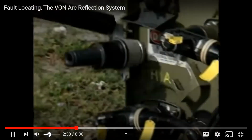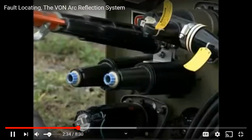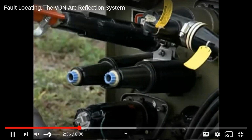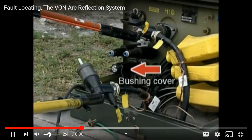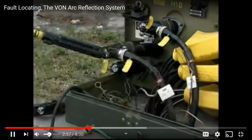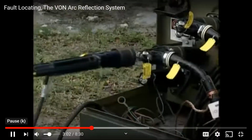Vaughn recommends using a feed-through device, so the parking bushing is removed and the feed-through installed. Make sure the cable that's not being tested has a bushing cap or cover to avoid inserting the high voltage lead into the wrong bushing. You can see here how close the feed-through is to the transformer bushing. That's why it's critical that any open bushing be covered with an approved bushing cover as illustrated here. Using a hot stick, the elbow is inserted into the feed-through and a grounding elbow is installed into the open bushing.